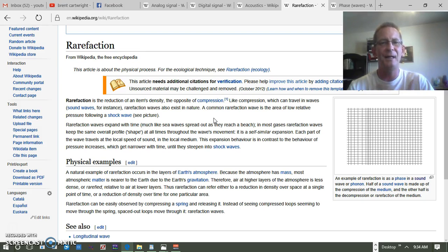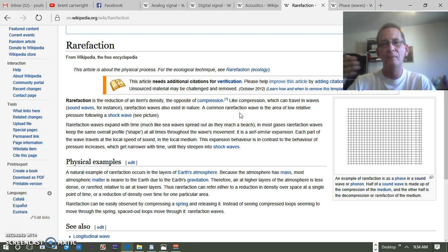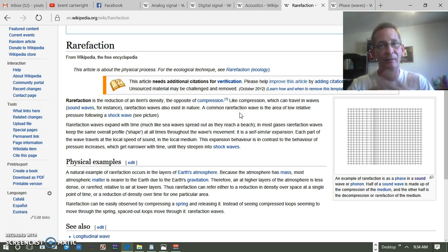Basically that's the same concept as what it's doing out in the air, rarefaction and compression, but it's doing that to the diaphragm on the condenser microphone, varying the voltage, so that your waveform may come out looking sinusoidal and clean, with the voltages going up, back down to zero, down, up, like that, or it might be very erratic as it captures that analog waveform from the air and converts it into an electrical signal.